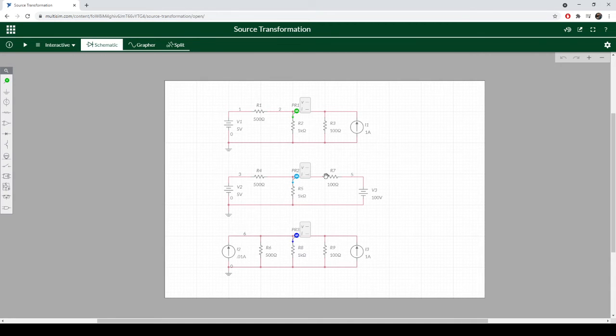We have to take into account nodes, so it's going to change the way, but it helps us simplify this down. We can now reduce this down into an equivalent circuit of just a voltage source and a resistance. Maybe to understand, say, R5 is our load, what is being applied to that in simplest terms. So then we could create an equivalent circuit for testing without messing with our entire circuit.